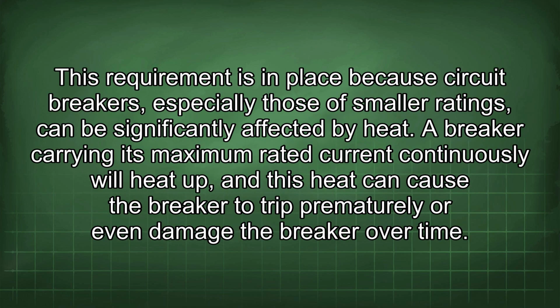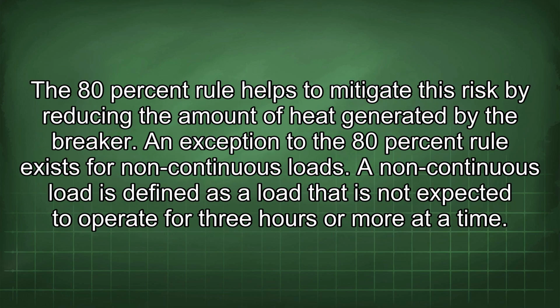This requirement is in place because circuit breakers, especially those of smaller ratings, can be significantly affected by heat. A breaker carrying its maximum rated current continuously will heat up, and this heat can cause the breaker to trip prematurely or even damage the breaker over time. The 80% rule helps to mitigate this risk by reducing the amount of heat generated by the breaker.